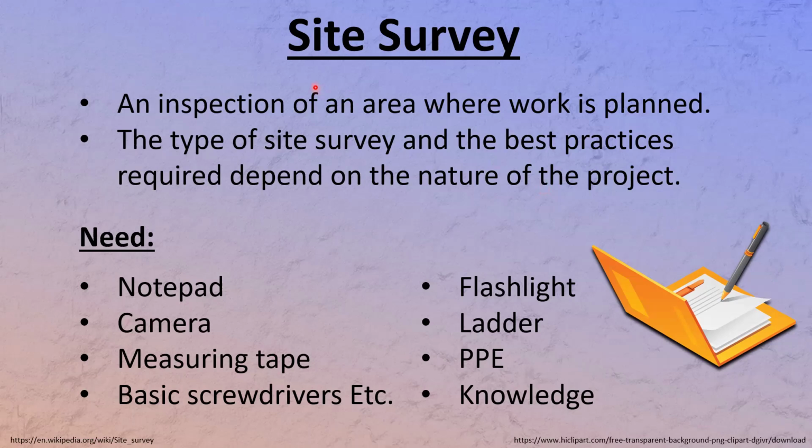So for that, what do you need? Well, you need a notepad, camera, tape measure, basic screwdrivers, because sometimes you have to open some panels and just take a look inside. Of course, you need a flashlight. A ladder is a good idea. Always show up with PPE, because in some cases you're going to have to have a hard hat or safety glasses or safety boots to enter certain areas. All right, so just be prepared. It just makes you look professional when you have those.